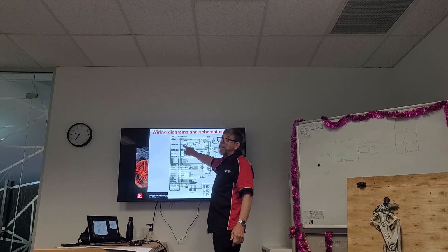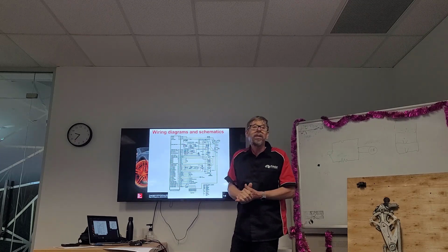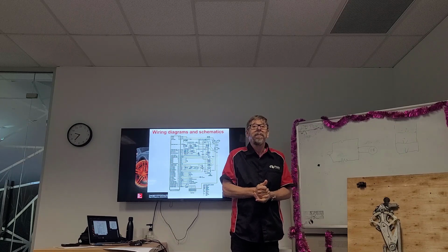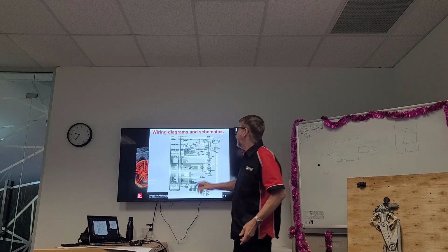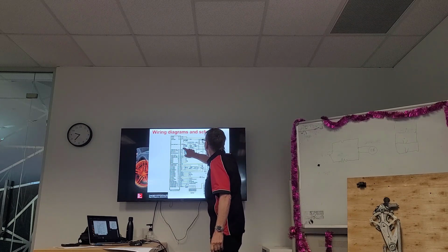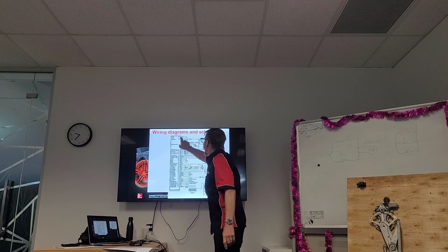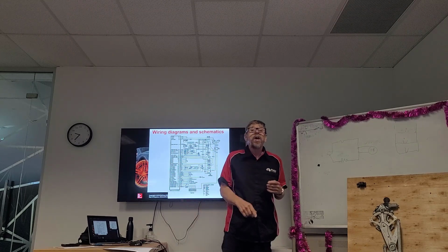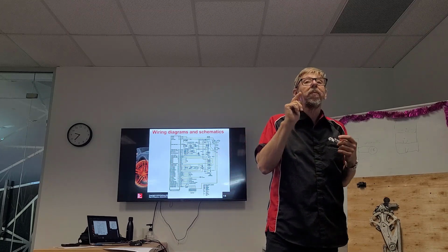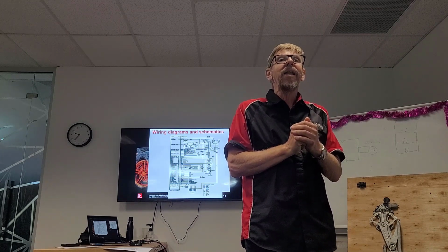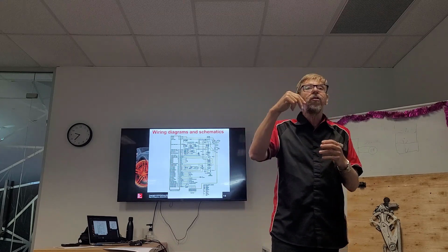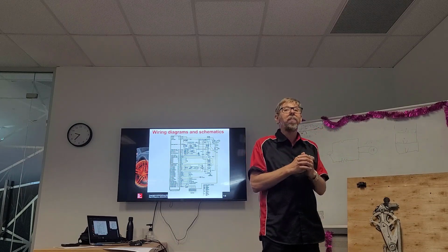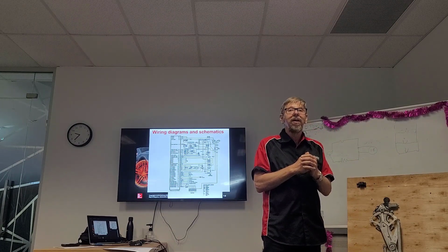So what's this one now? The one at the top. Positive. And where's the power coming from? Coming from the ignition. No, the ignition's here. What's it coming from? Oh, battery. What's in here? What's that? Power control. So the power control module is controlling that relay, and that's a power on switch relay, because the control module powers it up, and then it's controlled by the power. Does that make sense? Yeah.